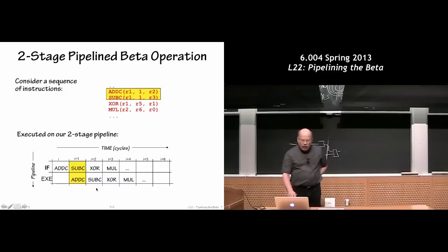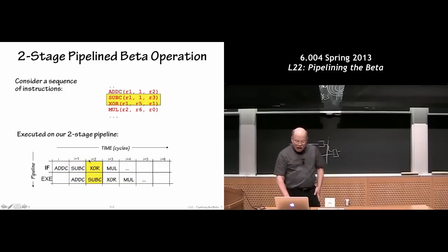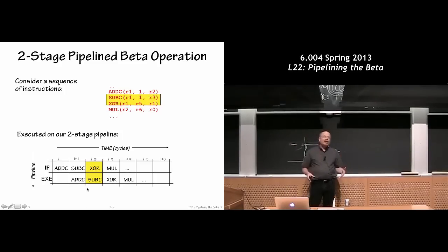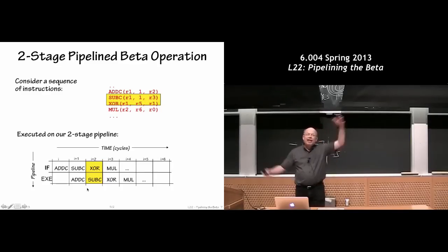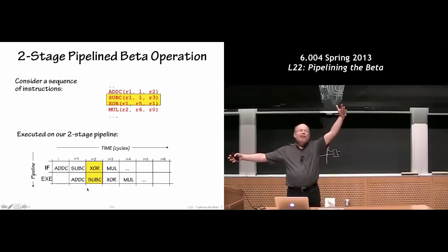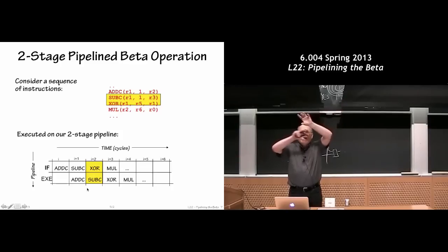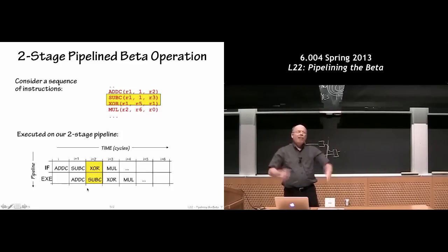And if all goes well, each instruction will just march through, and if we had a 5-stage pipeline diagram, we would have 5 different instructions all being executed in different stages of their execution, all in the same clock cycle. And if the gods were with us, maybe our processor would run 5 times faster, right? If we could equally divide all the delay that we need to invest in the execution of an instruction into 5 chunks, then our pipelining will actually get us quite a speed up. We're not going to be quite that lucky, but that's the basic idea.